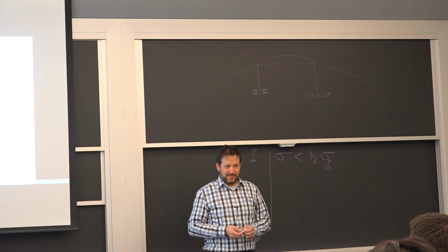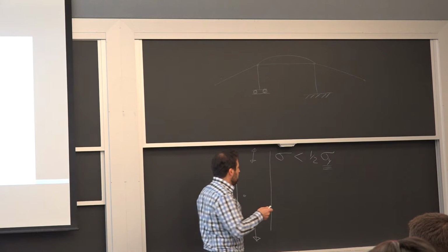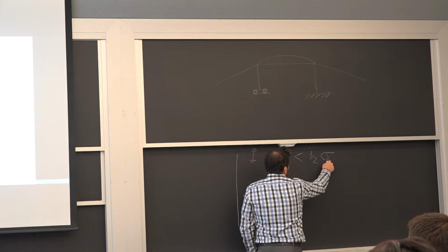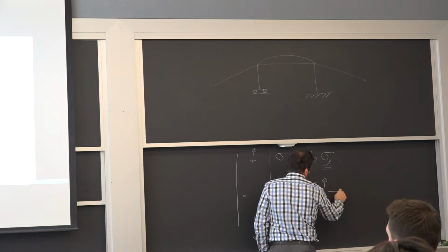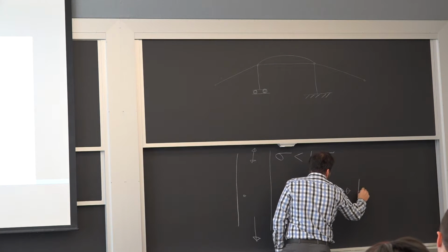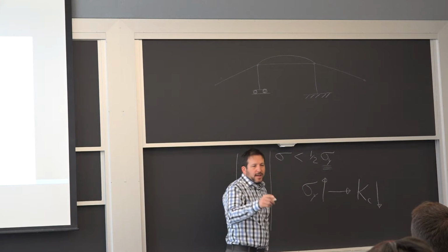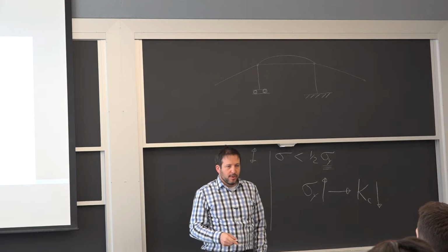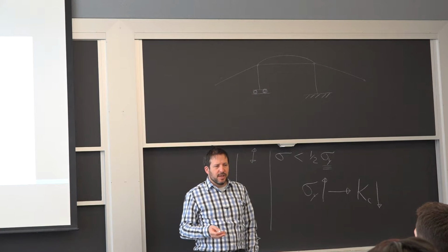Yes? To an existing crack. So as your yield strength is going up, generally for a certain category of alloy, your fracture toughness is going down. So in the case of our axle that we looked at together, it was structural steel, well, probably a relatively high-strength steel.